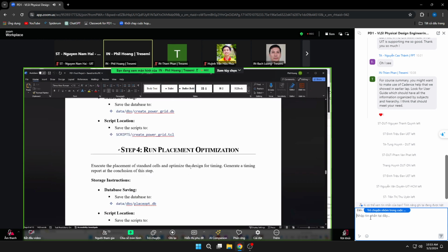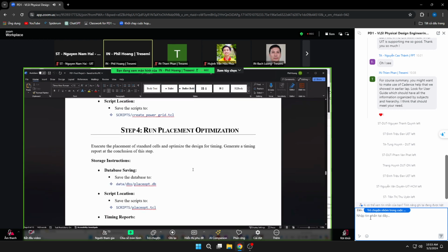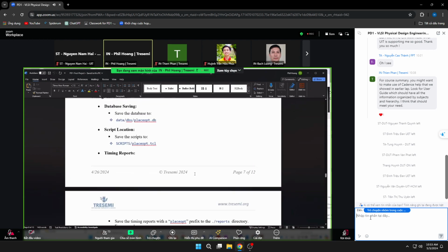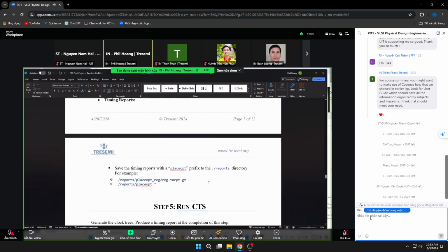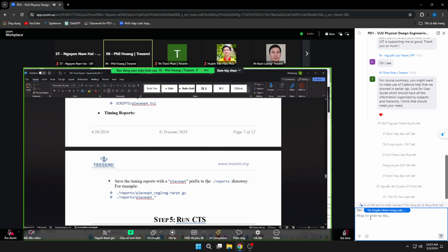So at this time you already have everything, and you just run placement optimization and you do a timing report. And if it doesn't meet timing, you iterate, you do things to fix the timing. And the difference between this and the previous one is really you run a lot of atomic commands called place opt. But these are not atomic, these are macro commands or super commands that do a lot. When you run this place opt, it does a lot of iterations inside.